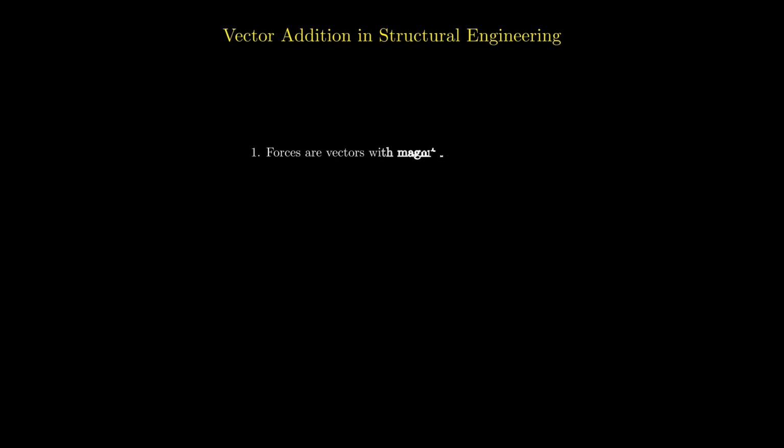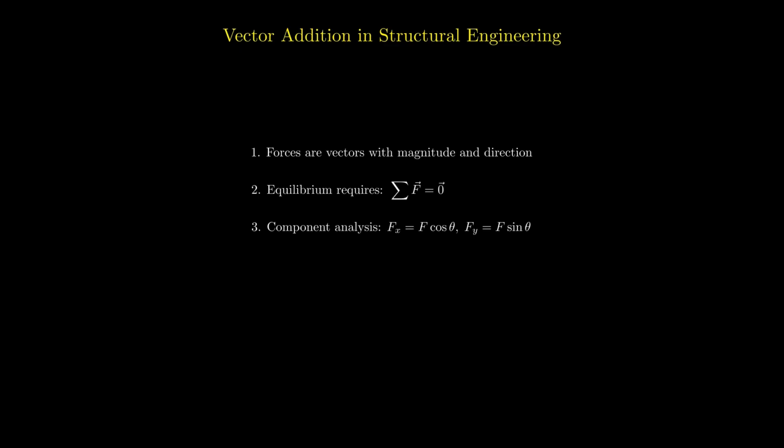To obey the principle of equilibrium, the sum of all forces should add to 0. If it does not equal 0, then the system is not in equilibrium. Now the components of forces act horizontally and vertically. The forces acting along the x-axis and y-axis are nothing but the product of the force times the cosine and sine of the angle along which it acts, respectively.